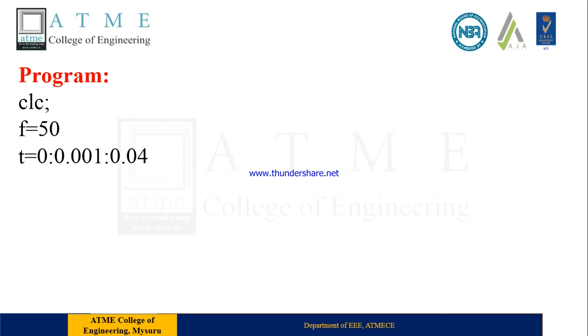I'm using the time period here as t equal to 0 to 0.04, in steps of 0.001. So I have the time period from 0 to 0.04. What you're seeing in the middle, after this, is indicating the sampling rate. We know the equation for sine is sine of 2 pi ft. So to get a continuous signal, we have sine of 2 pi ft, which I'm indicating as a representative signal over here.